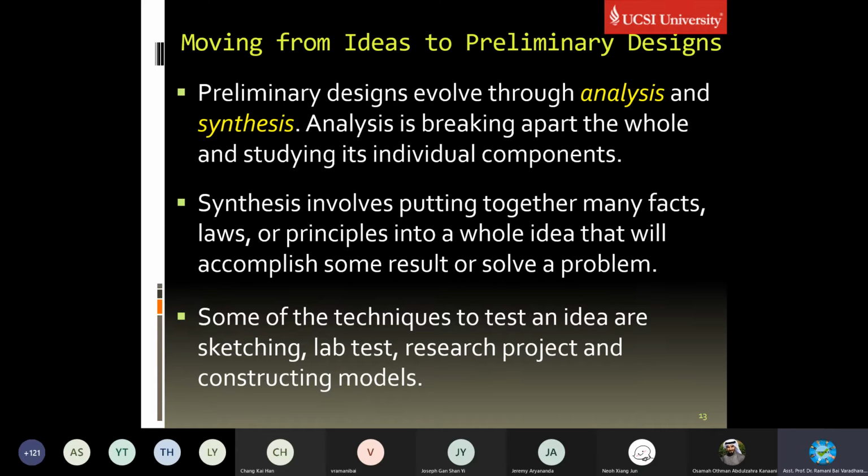What are the forces acting on it? What are the failures that will occur? What may be the dimensions of the foundation, the piers, sizes? Do all these for the foundation first, and then go to the basement, then the superstructure, then the other levels. So do it step by step, from a bottom to top approach or a top to bottom approach.